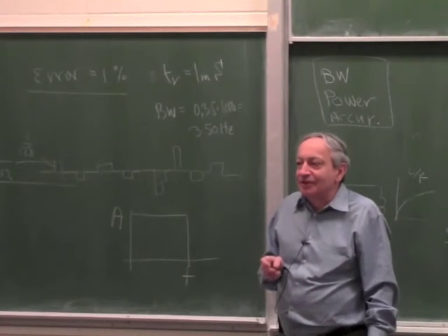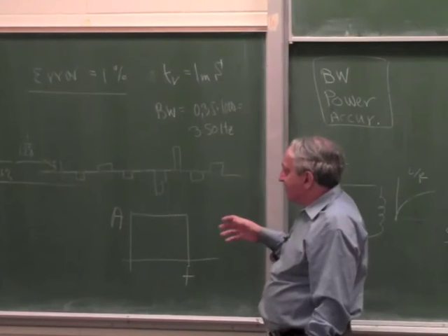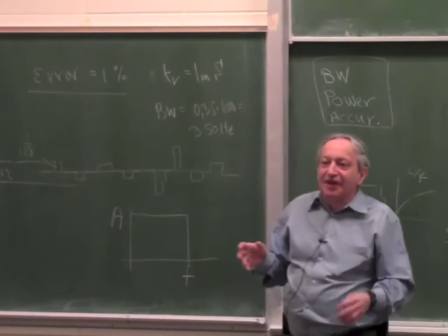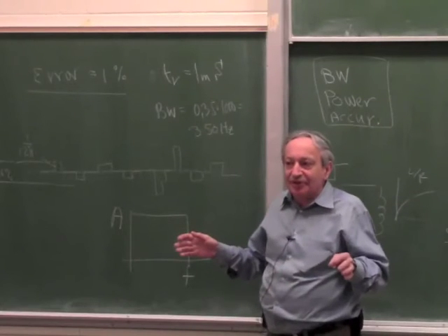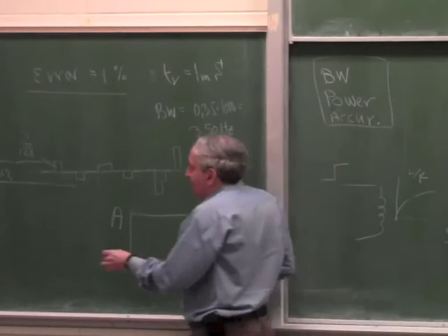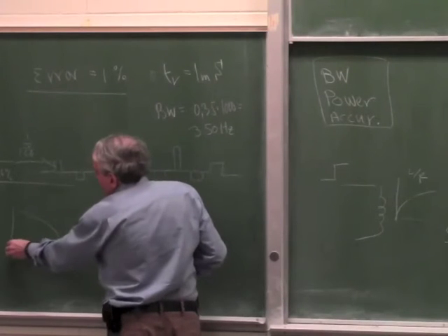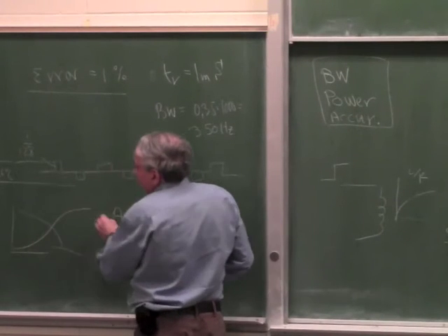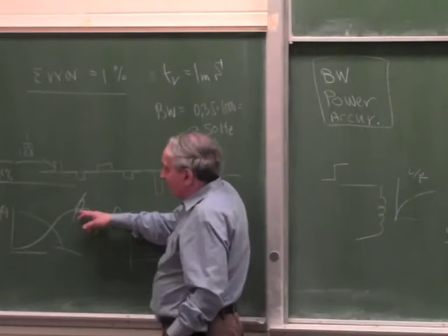Ringing? Okay, so there are two things bad with that, because there is a relationship between the phase and the amplitude plot on any network. So if you have a simple network like this, the phase plot looks like this. This is phase and this is amplitude. So it goes up to 90 degrees phase shift.